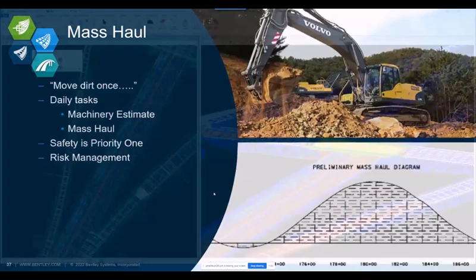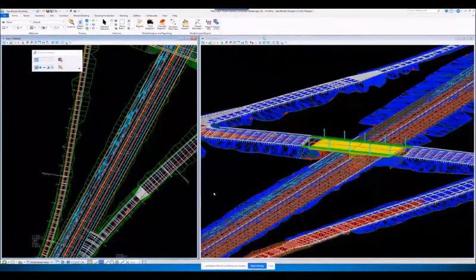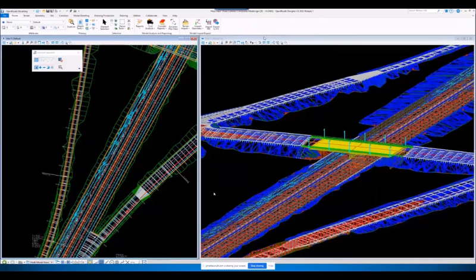If you have a three-dimensional model, and you start looking at something a little bit more particular, like I have a northbound, southbound I-95. I'm looking at it, and when I'm constructing this, I can only move northbound 95's dirt at one time. I can't move southbound because I have to move traffic somewhere to do this project. So I'm going to move everything northbound to the southbound lanes, put them in the cattle chutes, and all my earthwork, I'm going to move on to the northbound side, in this case, the right side of this model.